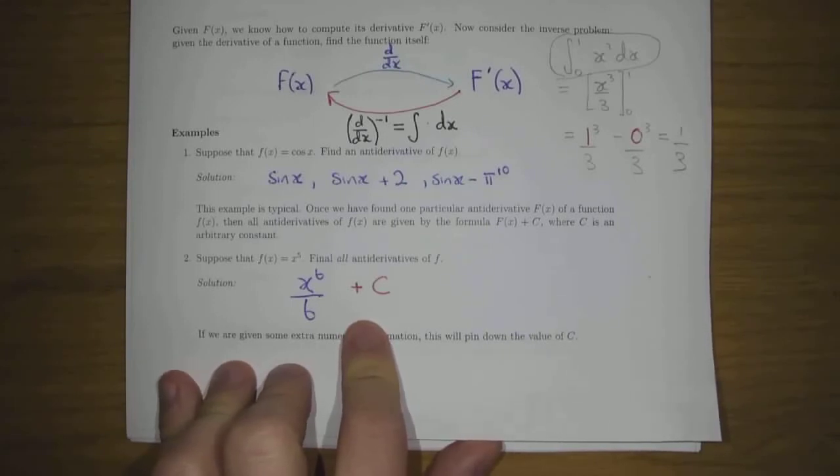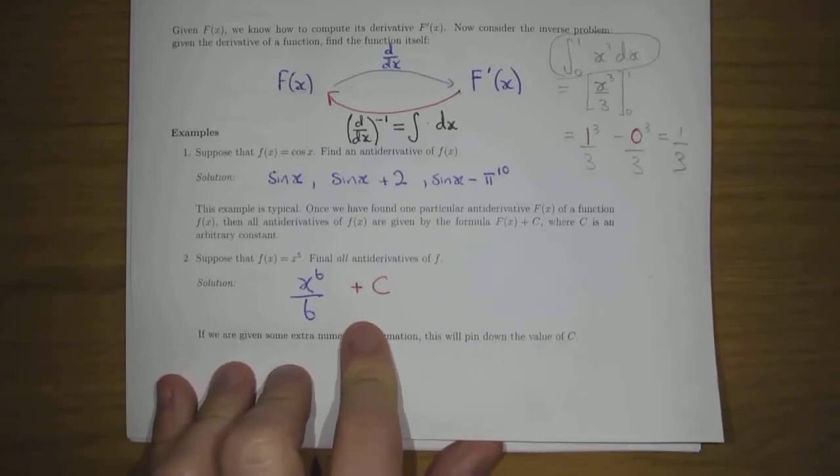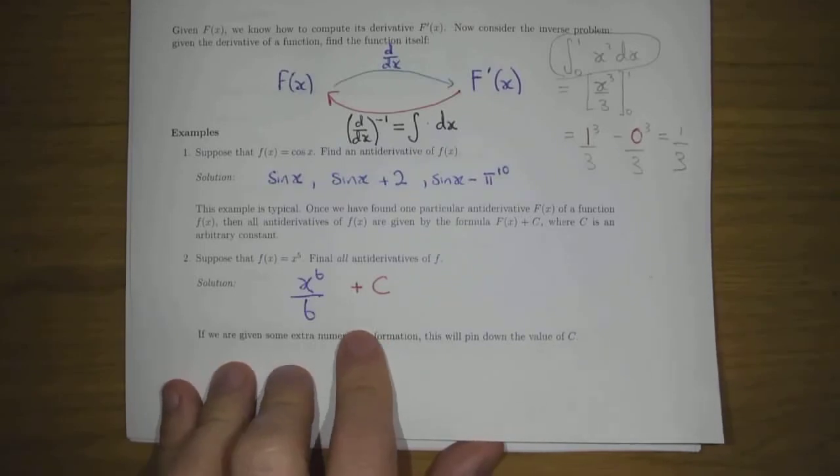One of them is going to be the reaction at A, at the left side of the beam. One of them is going to be MA, the bending moment at the left side of the beam. One of them is going to be called C1 and it's related to the slope at the left support. And the other one is C2, which is related to the deflection at the left support. And if it is supported, that's going to be 0. Indeed, that's always going to be the case.